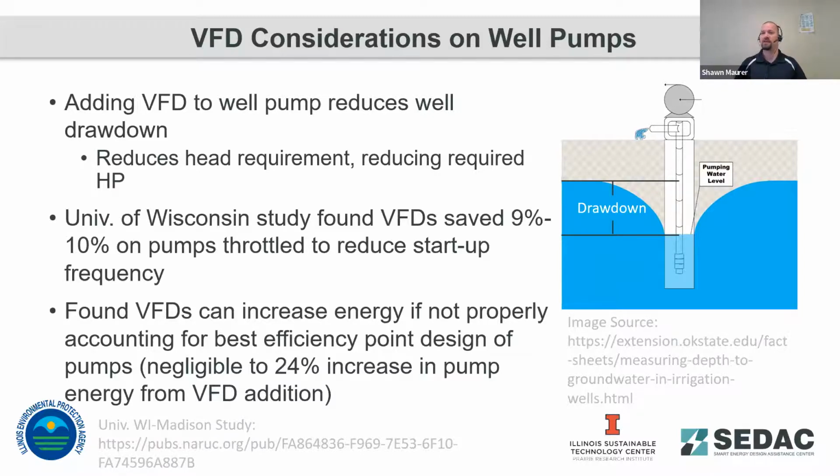And then in actual operation, usually the pump system curve shifts a little bit to the right and actually hits that best efficiency point. But as time goes on, corrosion starts to build up in pipes. You start getting filter clogging in the bottom of the well. It starts to move back to the left. And then when you try to put a VFD on there, you start to lose efficiency right away, and that can increase your energy consumption. So it's very important to understand the interaction between your system and the pump that's applied to that system to see if a VFD is going to be cost effective for you.